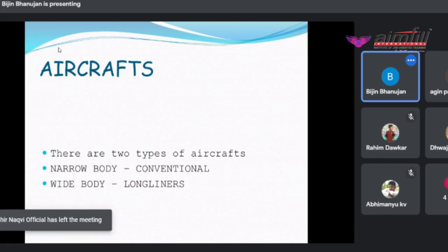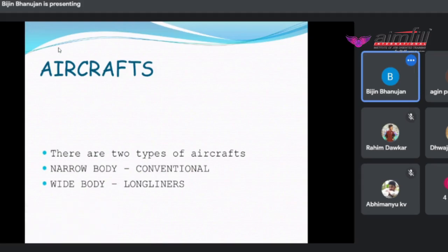Okay, don't go too deep. It's the ATC towers. You will not have enough ATC towers when you're traveling over a sea, and you need to also check the ETOPS condition of the aircraft, and also the commanders, that is the pilots, must have the license of operating an ETOPS flight. So when these all add up, when you cross an ocean, the flight plan becomes much more thick, and you will have more complications regarding that particular sector.